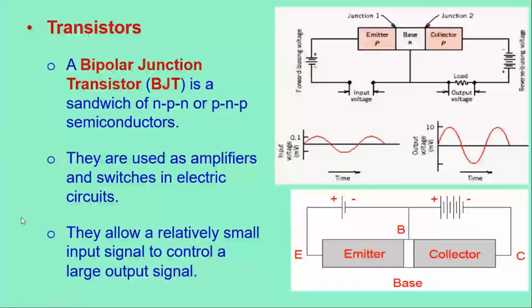So we also have the transistors. So here we'll actually look at the two types of transistors. We have the bipolar junction transistor. So this is the most basic type, BJT type, where we have a junction. In this case, we looked at the diode, which was a PN junction, while for the transistor, there are two types of sandwich, where we have the NPN or PNP.